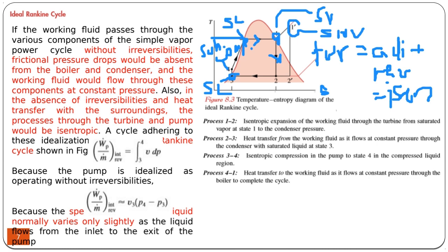And when we use superheated vapor, you can see that the exit of the turbine is drier than the exit of the saturated vapor turbine. So the reason why we are using superheated vapor is both to increase the efficiency, and also we would like to have a turbine that does not work with liquid droplets inside the steam. So we would like the steam to be as dry as possible.